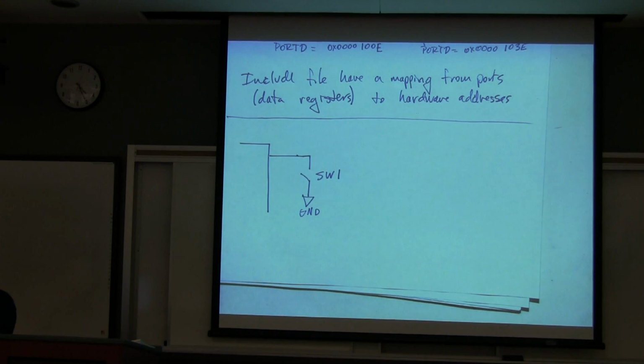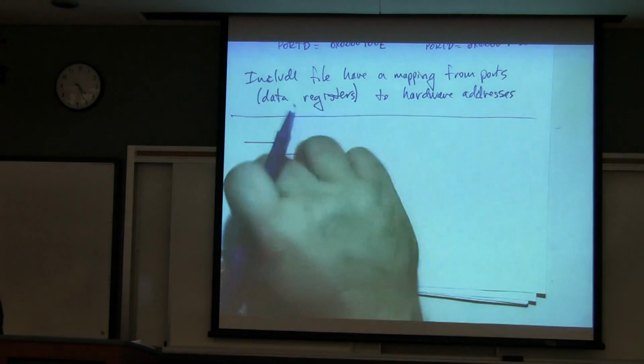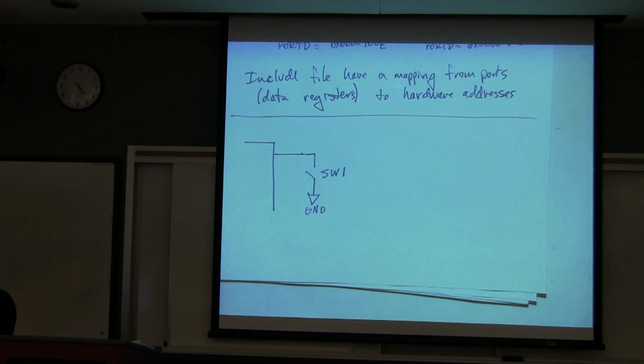So because we have not tied this specific input to 0 or ground, you have no idea what that is. So it's just floating out there. Now when you push the switch, what is the voltage going to be? 0. You know that for a fact because you're suddenly tying it directly to 0. So when you release the switch, you don't know what it's going to be. So what do you think you want to put it at when the switch is not pushed? VCC. All right, VCC, or as close as possible.